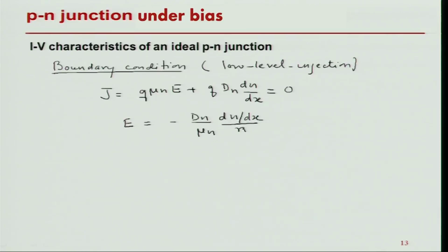now we have earlier looked at E from the electrostatic point of view and calculated the field in the junction. Now, here we are doing the same thing, but we are looking at a situation where there could be a bias also. Now, in this situation I will use the Einstein relationship, which relates the mobility of the carriers to its diffusion constant.